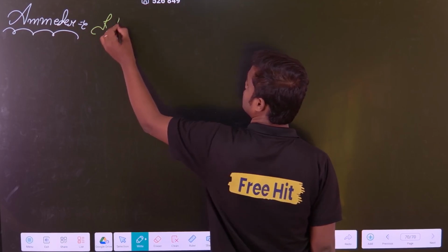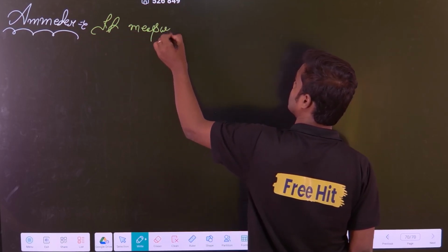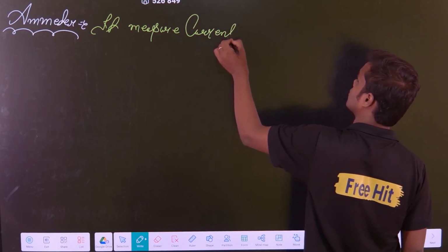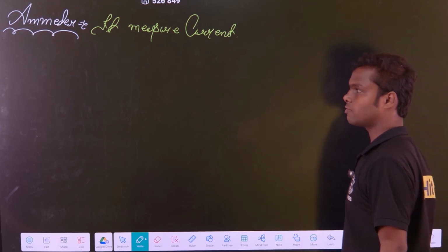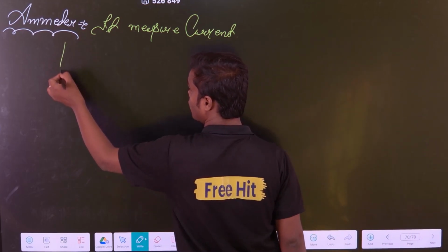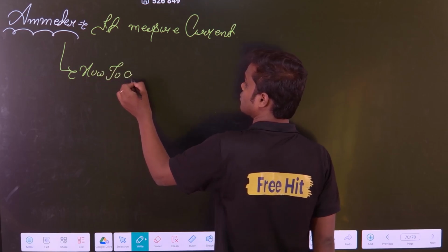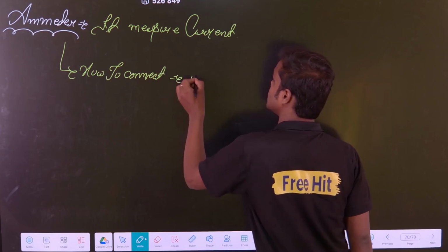It measures current. Simple. Wherever you connect it, it will measure the current. Now the question is how to connect it? It is connected in series.